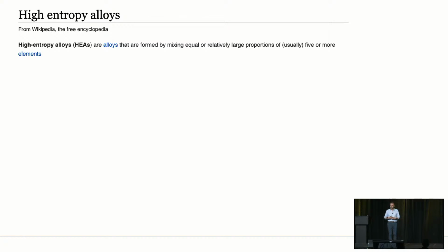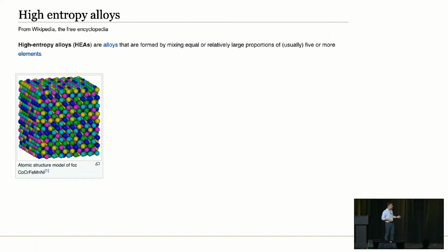So if you take an alloy and you have 20% of any metals you can think of, let's say zinc, tin, gallium, iron, and nickel, conceivably, this theory of high entropy alloys says it will be single phase. And interestingly, those that conceived them found many examples of this happening, which is kind of remarkable from a metallurgical point of view, I guess, in our era or our career. So this is what an atomistic model looks like of this alloy, which is cobalt, chromium, iron, manganese, nickel. So a lot of transition metals there.